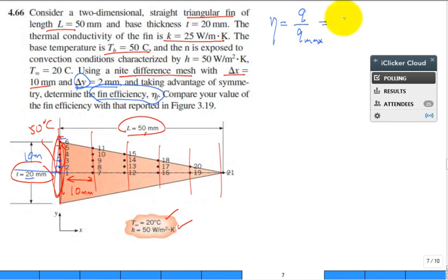So you would say, well, if I calculated each of these temperatures, node 6 and node whatever that is, 11, then node 15, etc., what I could do is get an average temperature here. So the Q actual would be the convection coefficient, my area, some temperature surface average along that edge minus the temperature fluid.